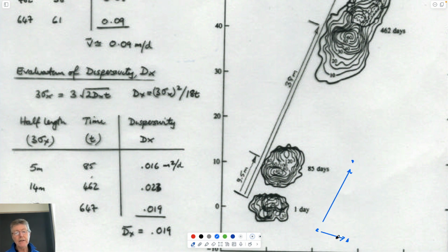If there's no gradient laterally, you take this as being the direction you'd next look in. Maybe if you know the heads and you also know the permeability, then you know that the velocity traveled is equal to the hydraulic conductivity times the head gradient divided by porosity. And so if you know this, you know that length is equal to